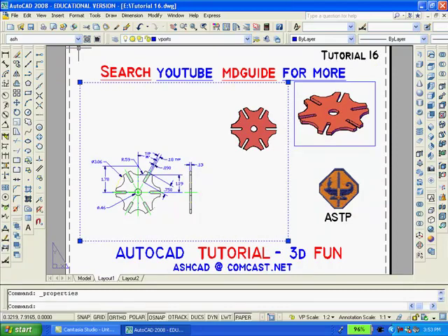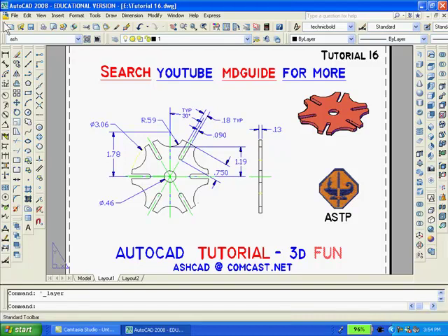Once the scale is set, double-click inside the large viewport to gain access pan so that only the 2D drawing is visible. Then double-click outside the viewport to get back into Paperspace. And finally, if you don't want the rectangles to be printed, go to the Layer dialog box and freeze the layer viewports where they are located. The drawing is now complete.